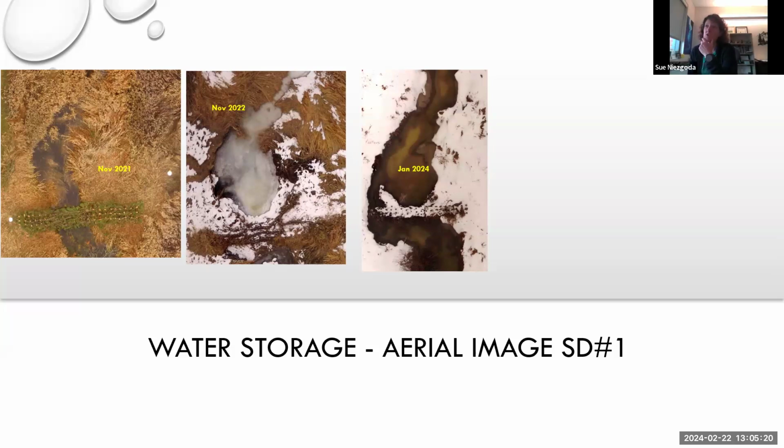And so we had a lot of erosion that happened right off the bat because we didn't get the sealing that we wanted. We also have an issue out here, well, it's not really an issue, but it happens. The middle picture there, you can see the ice layer. We get ice that forms over, essentially putting a lid on the creek in the winter, and the water is still flowing under that ice lid. But when it runs into the BDA structure, if it has that ice lid on top, it can't go over the structure. So it's looking for another way to get around, and it's been tending to scour underneath, so under the weave material.